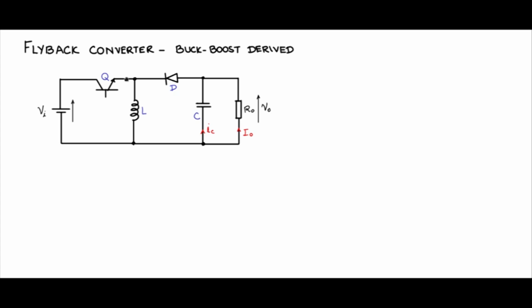The emitter is lifted up, floating. It is much better to have the switch ground based, and the ground based drive is much easier to make. So without loss of generality, we can move this switch from the top rail to the return rail, maintaining the flow of the current path in the same manner.